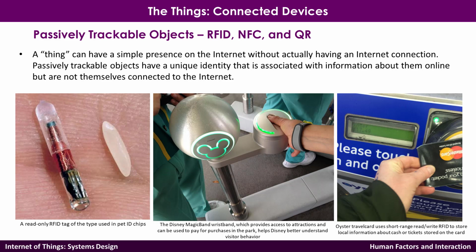The point to make is that because they are not powered devices most of the time, there are some active variations, but most of them are passive, which means they are not connected to power. They just respond to the reader. The reader would technically emit a signal, and the signal would power the device temporarily, and that temporary power allows it to read what is inside the particular tag.